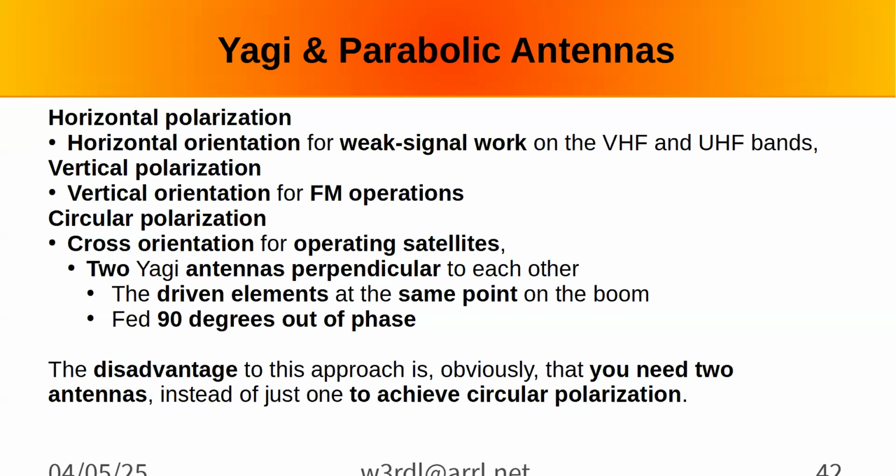Well, in the case of vertical, if you're doing point to point, you have to have a vertically polarized receiving and transmitting antenna. If they're cross polarized, you lose a lot of signal. If you're doing horizontal and you're propagating by refraction off the ionosphere, it doesn't matter because once it refracts, it becomes elliptically polarized. It's no longer linearly polarized.